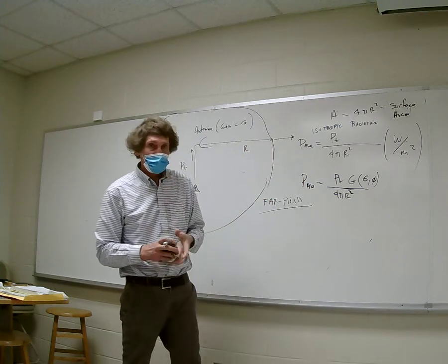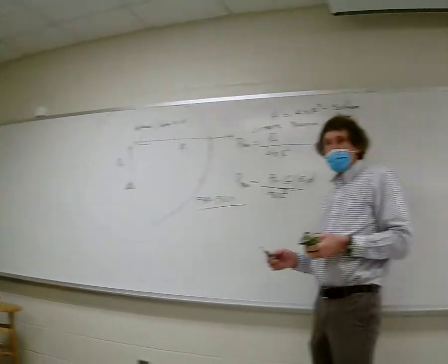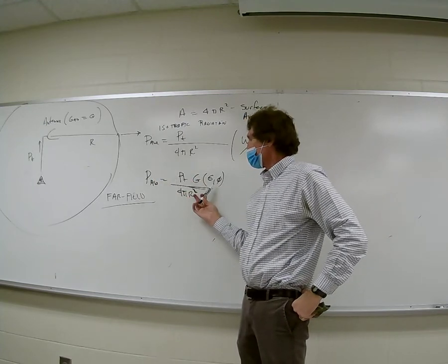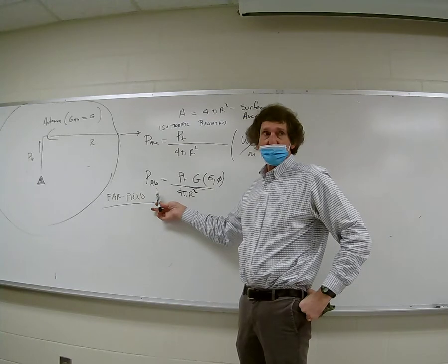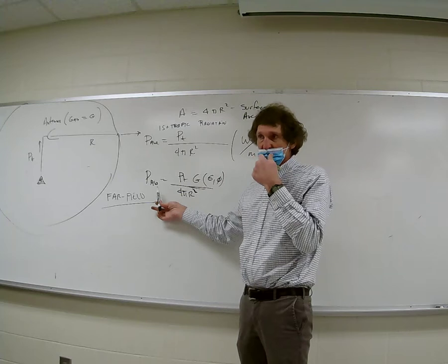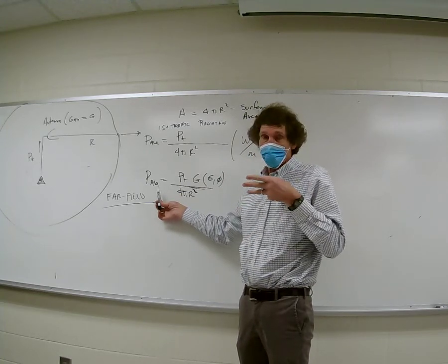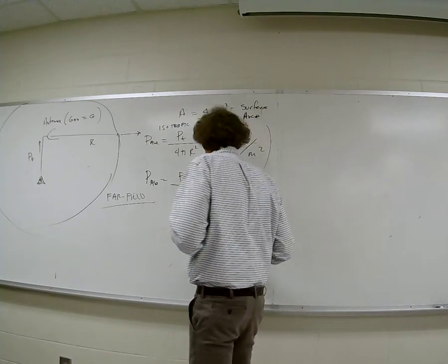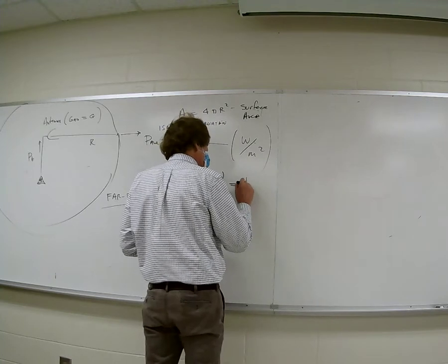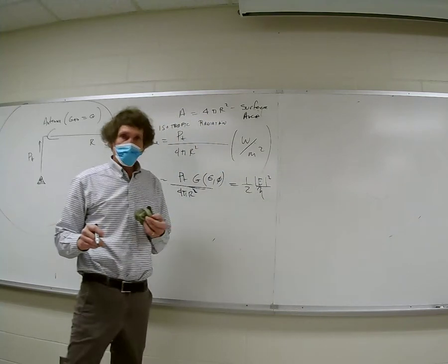So the question is, how do you get the electric field density out here from the antenna gain and the power transmitted? If I'm out a distance R away, and I know the gain of the antenna, I have a power density in watts per meter squared, right? I'm assuming it's in the far field and it's radiating, correct, class? It's not near field where you have electrostatic and magnetostatic energy. Well, in the far field, what would the electric field be? Wouldn't it be 1/2 the magnitude of the electric field squared over eta, the eta of free space?